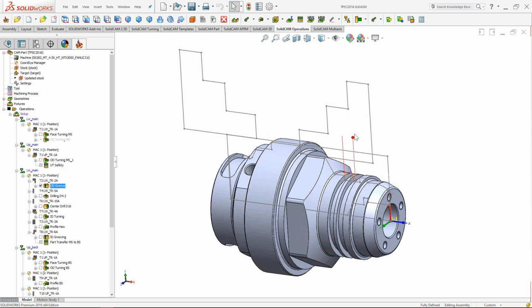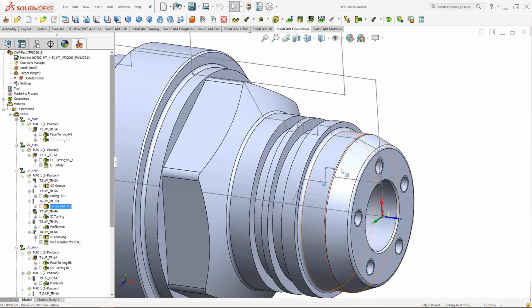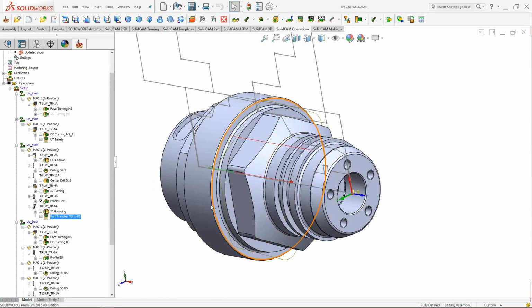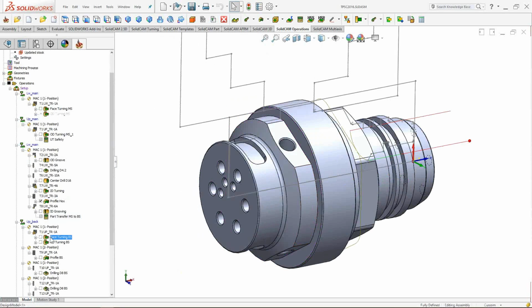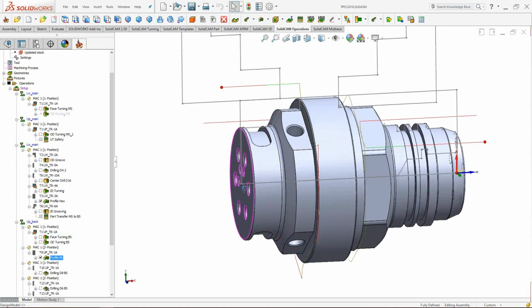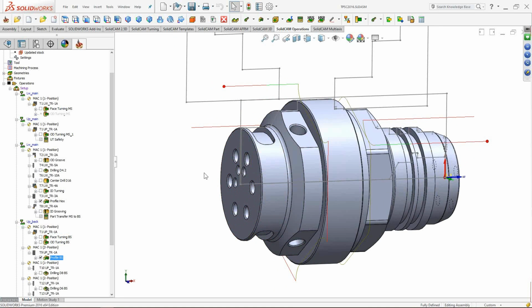As well, here we have something on the groove. Then a few operations with drilling, center drilling, and here, of course, we have the internal turning as well as grooving, and doing this profile, these surfaces over here. And after that, we have the part transfer and do the machining, pretty much the same thing. We have the face, we have the outside, we have finishing those surfaces over here, and some of the holes that are presented on the radial position and on the face position itself.